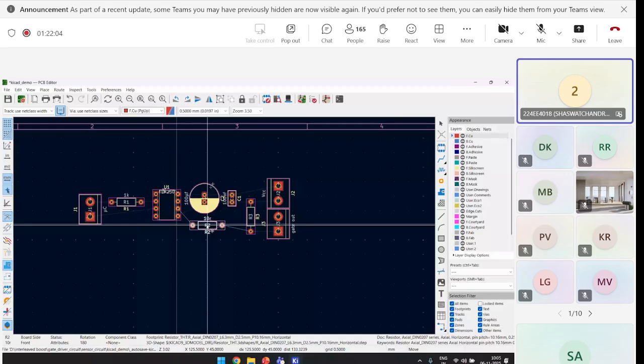I'll click on this route signal track. You click on this, then you can go and click on any of the terminals. If you click on this terminal, KiCad will actually show you where this terminal goes. So you can't misplace it. I can't connect this to a wrong terminal. See, I can't connect to any of the wrong terminals. So KiCad doesn't allow you to place connections between wrong terminals. That's a nice feature for it. And I will connect here. You can go ahead and connect every single connection. Sorted this.